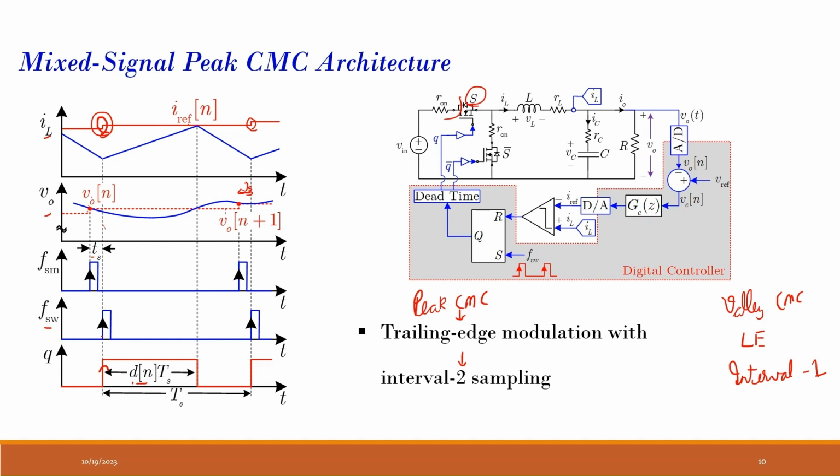Okay, and it's not that instantaneously everything can happen. There is a delay. The delay might be small, but the delay is there, and for safety you must have that guarantee that I have taken the sample at this time, and it is guaranteed, even in worst case condition, that it will be able to generate a reference by this time before the switching frequency clock comes. Okay, so by that way you determine how much delay is required. Okay, and then you use that computation to generate your new duty ratio.